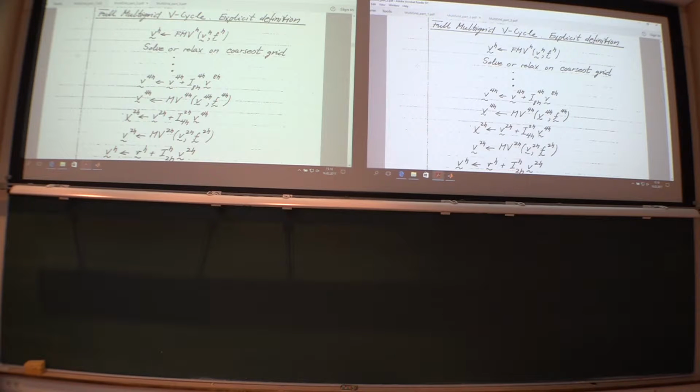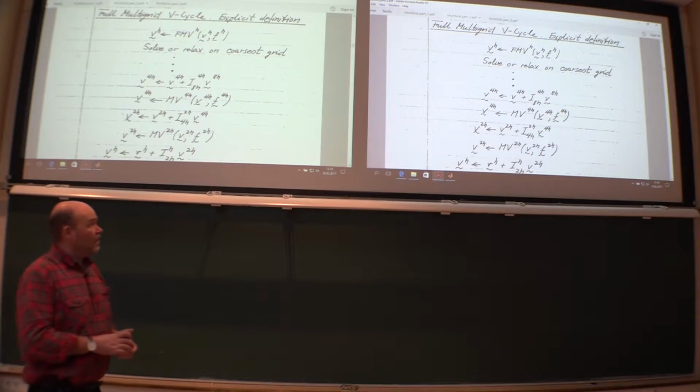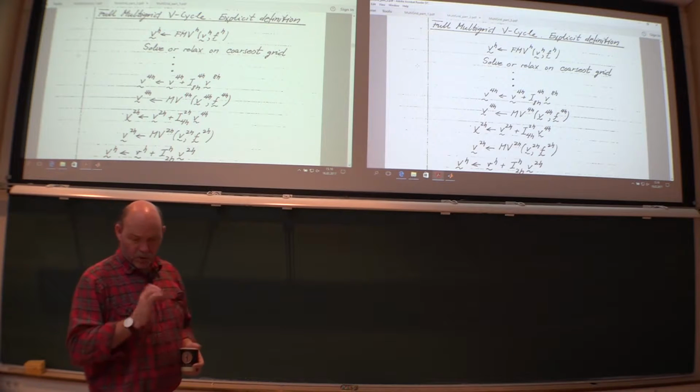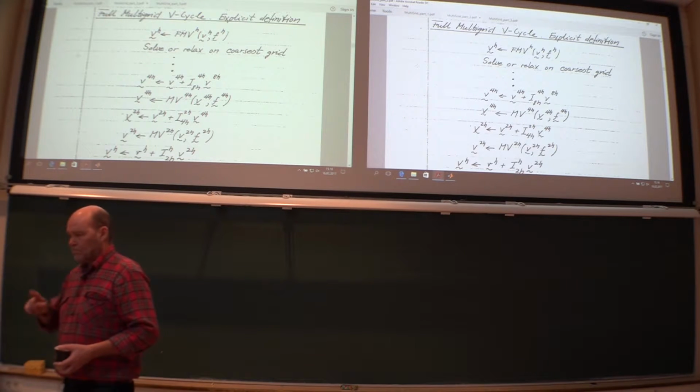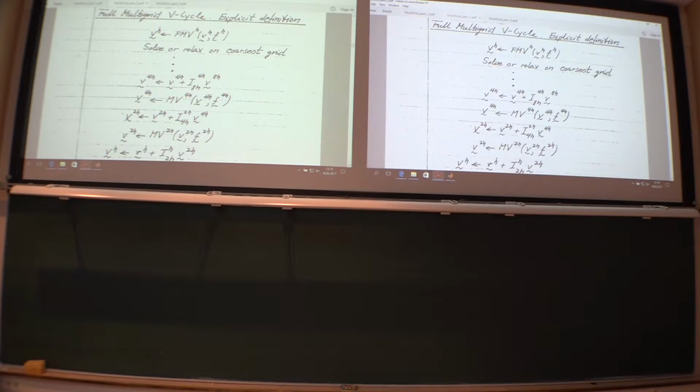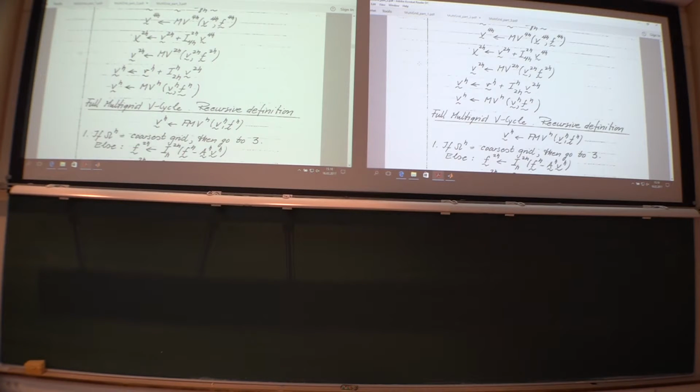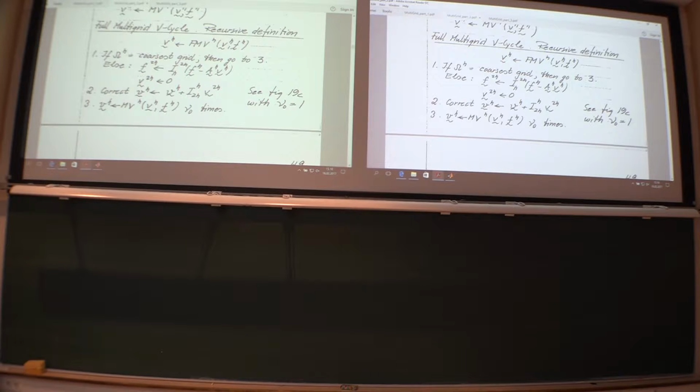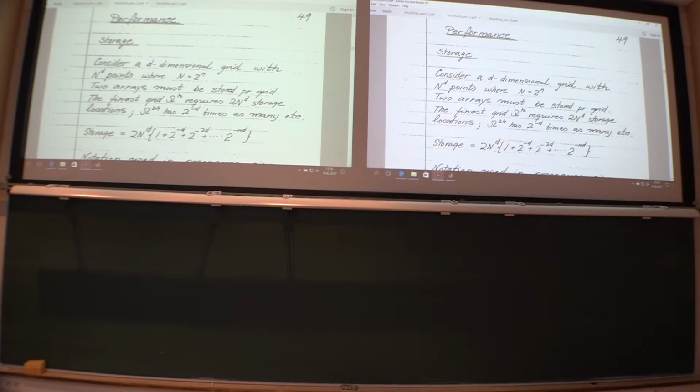And then also this full multigrid method. So you start on the coarsest mesh and then nest your way up to the finest to start to find a better initial solution on the fine mesh. Yes, that's an option. So yeah, we don't have to go through all this.